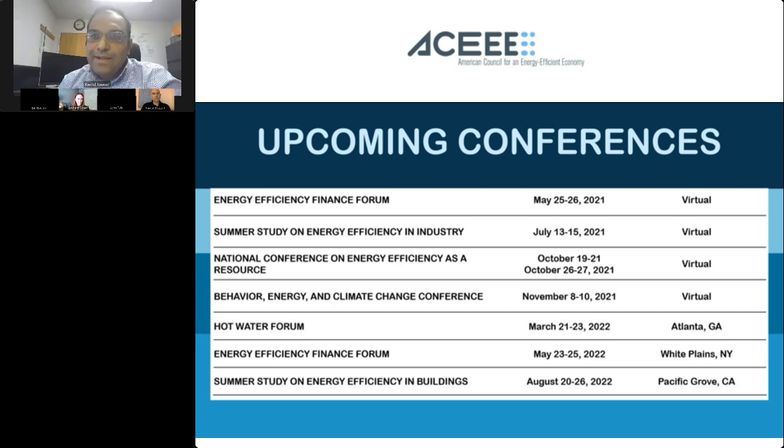So I can actually give a little background on this. We actually have done some analysis on looking at the degradation of performance of heat pump water heaters when we are looking at different ambient temperatures. And obviously, some people report it as a linear trend. We have observed it's a little non-linear, but obviously as you go to a lower ambient temperature, your UEF decreases.